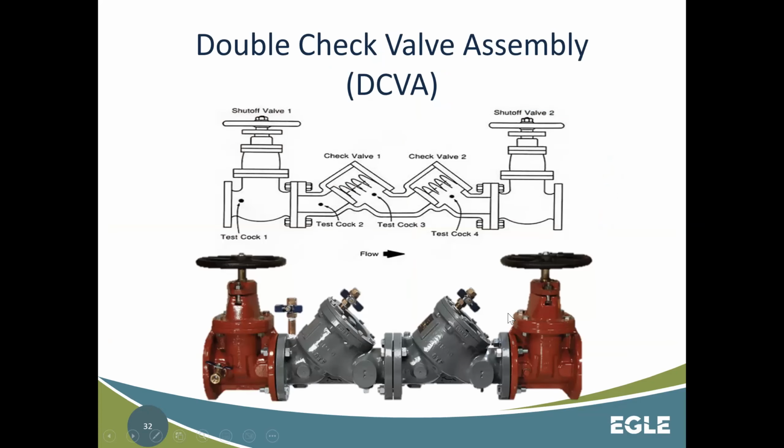All right, this leads me to the next thing, which is considered a double check valve assembly. This double check valve assembly is a testable assembly. I get that 100%. It's called an assembly, but double check valves are different than RPZs. And the biggest reason they are different is because they are for low hazard application or aesthetics.